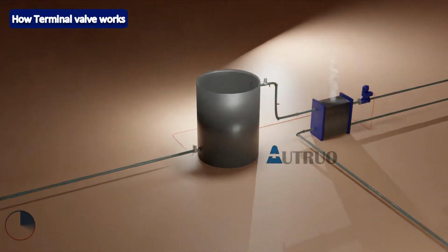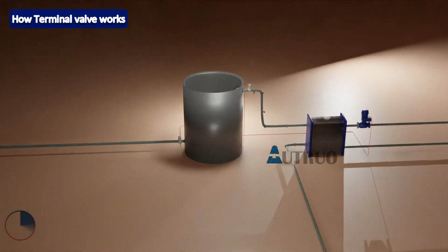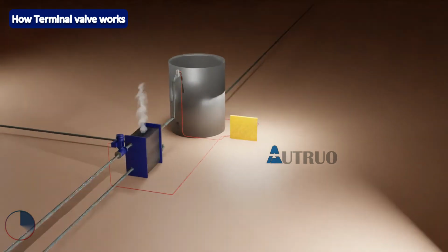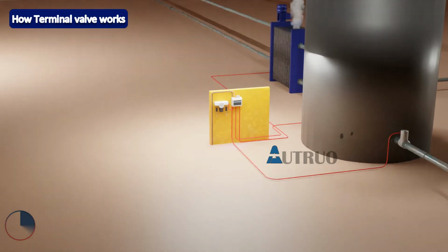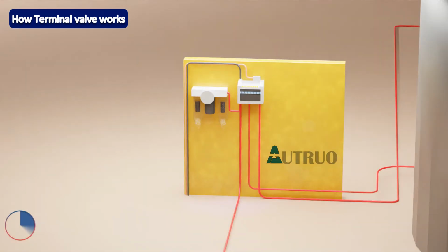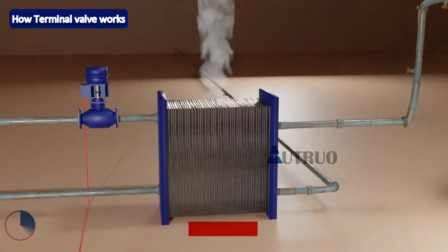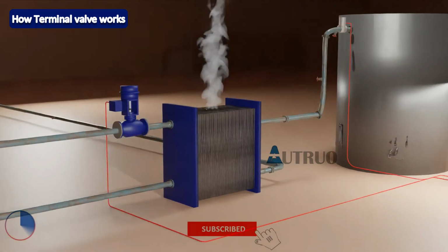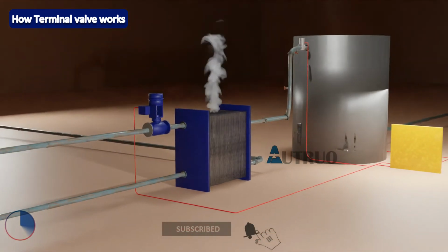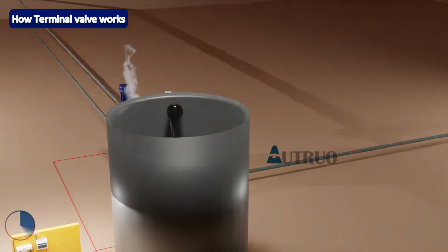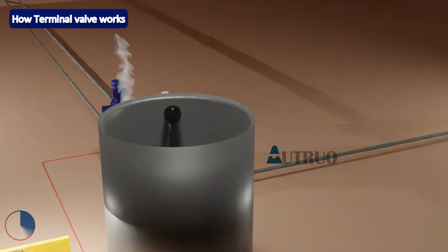It is an electro-pneumatic device that is used to control the supply of compressed air when required. It has only one air supply inlet. This inlet is where the compressed air coming from utilities will be terminated. It is at this port that it will be distributed to other channels. These channels are where the field instruments will be terminated.